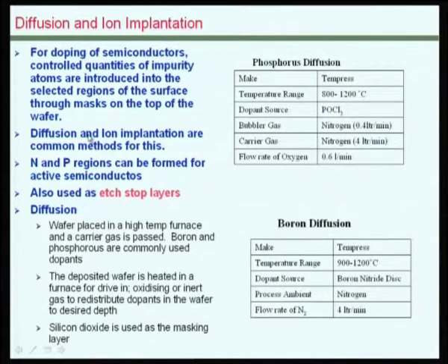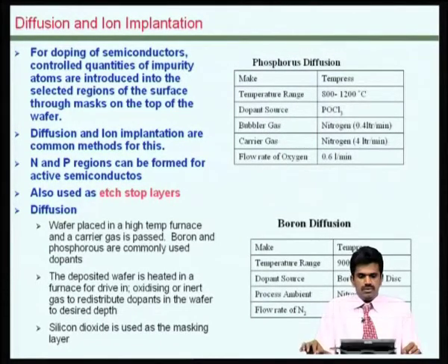So, when some regions of the surface are doped, they react less with the reagent and hence cannot be dissolved as compared to other regions, and that is very useful in building certain geometries on the silicon wafer. Hence, diffusion is an important step after transferring pattern in building microsystems.